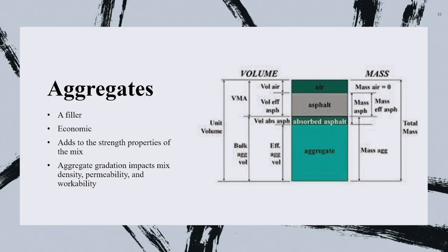Then you flip the barrel, you make some sort of filtering for the water. Sometimes we use burlap or cloth that we use for curing of concrete. You let it dry, then the aggregate now is what we call SSD, saturated surface dry, meaning from the inside it is saturated, from the surface it is dry. Then it's now optimized aggregate to be used for the concrete manufacturing.